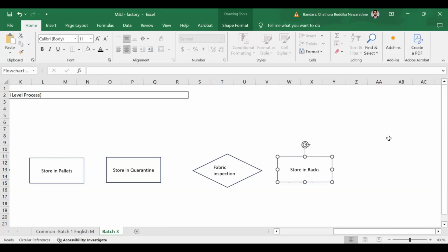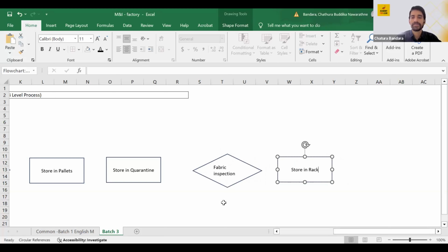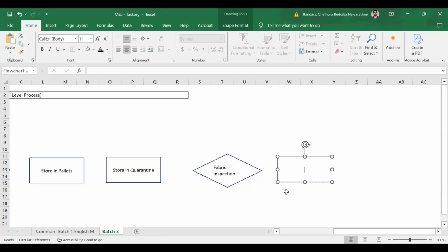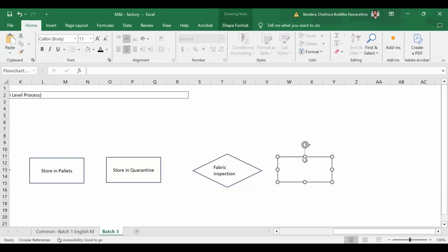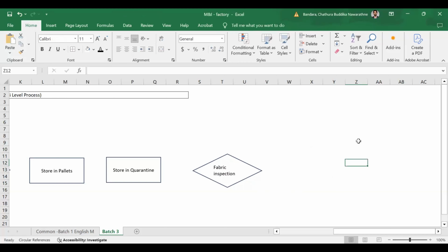If the fabric inspection passes, there will be another process to verify the color grouping. 100%. If it passes fabric inspection, they will do the color grouping with the color trim cards. Then they will do the color grouping based on the color grouping verification from the IQC. In fabric inspection QC, they will group the color group within the batch. Maybe one group, two group, three group, A, B, C.